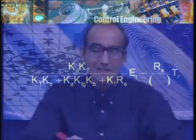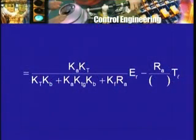So I get products of several coefficients and added up. As I told you, this now does not immediately have any significance. This whole thing multiplies ER, and then now I will bring that minus sign which was inside, I will bring it outside. So minus the coefficient that multiplies in the numerator will be Ra, that's all, because Kt Kb is what we are going to multiply numerator and denominator, and the denominator will be the same expression that appears in the coefficient multiplying ER. So this is the expression for the speed in terms of the reference voltage and the load torque.